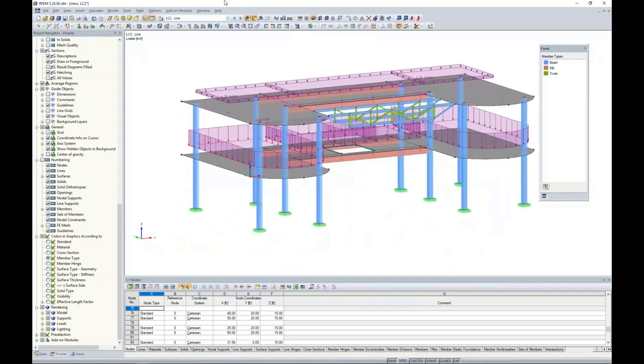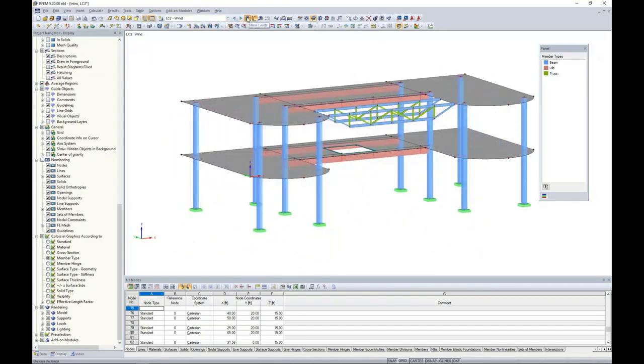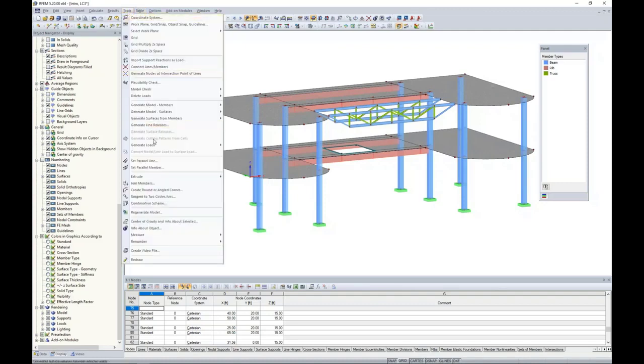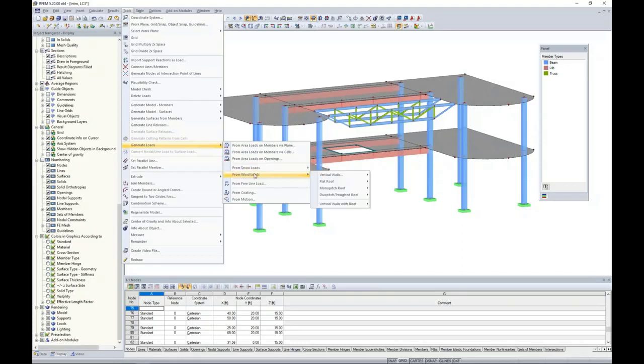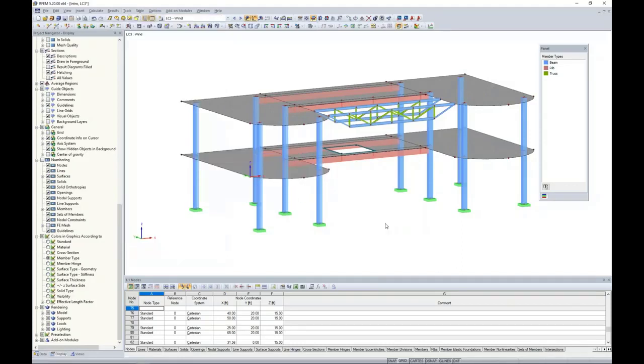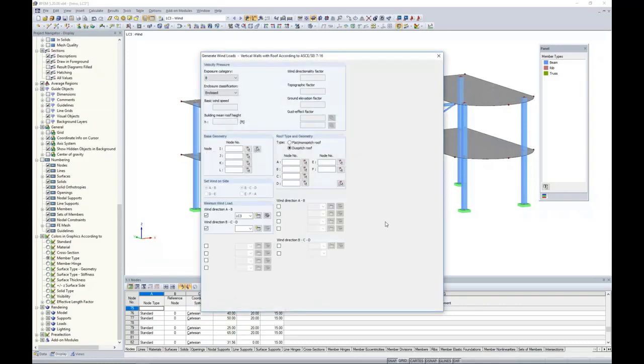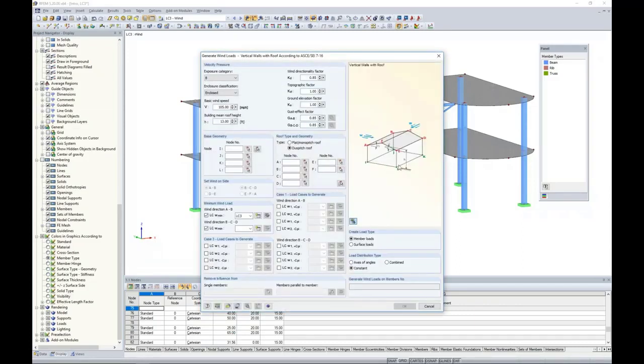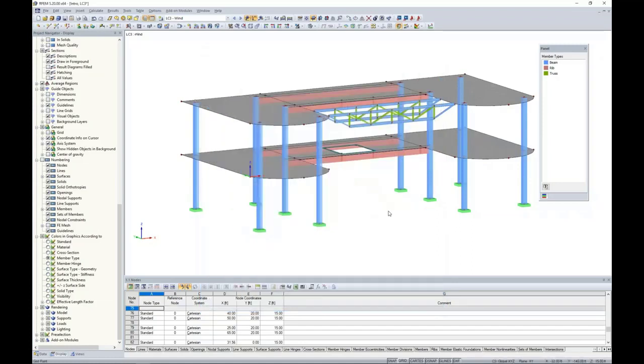Okay, so for the wind load scenario, under the Tools option, Generate Loads, we have snow loads and wind loads. These are a couple of load generators, but keep in mind that we do have the ASCE 7 here. It really is only applicable for rectangular type structures such as this. The minute that we get outside of these geometric properties, then we need to manually apply the wind loads instead. So we're certainly outside of this realm for our example today, so we cannot use this generator.